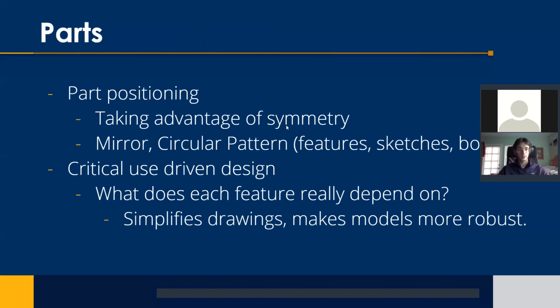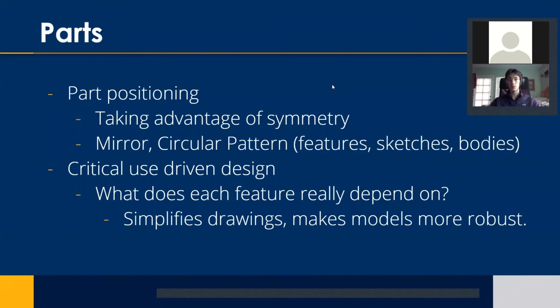Yeah, so that's a gusset. Now I'm going to go into a little bit more detail about some of the finer details of best practice for part design. And this will kind of help us save some time. So the reason why I was able to do a mirror image of that gusset is, well, partially because it was centered in the planes.